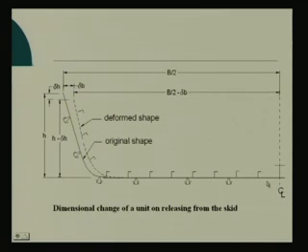In a section, you have the bottom shell which is stiffened by longitudinals, and part of the bilge plate, and a part of the side shell, but you can consider it to be a small unit, one part of the double bottom, right.